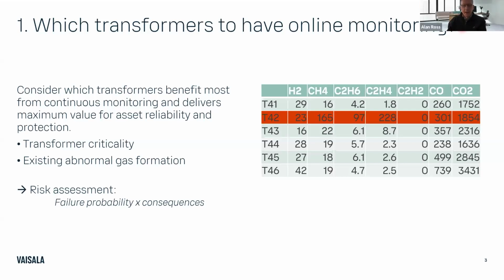Okay. So if you put a plan together and say, I'm going to do a combination of multi-gas monitors and check engine hydrogen monitors, you can leverage your budget and, if anything, if you have 10 transformers in the same class, it'll tell you which one to look at first because the hydrogen check engine light goes off, and then you can do a sample and make some decisions there. Okay, it's an interesting thing that's happening right now. Case by case, yeah. Okay, perfect.